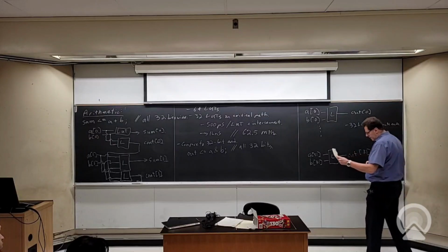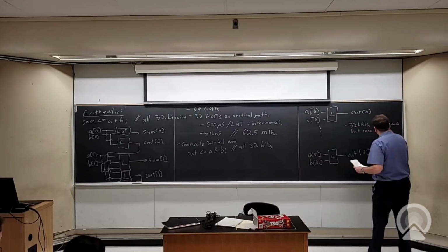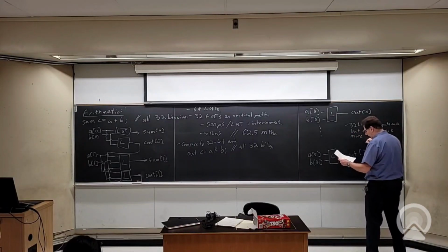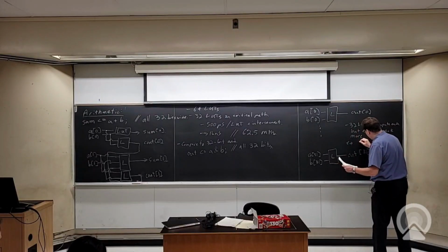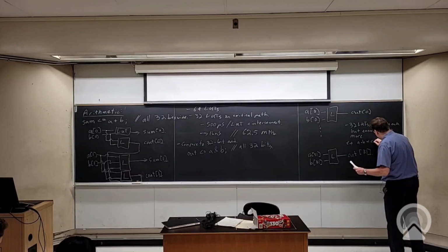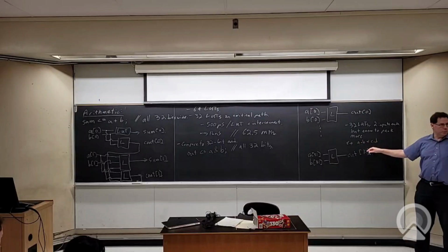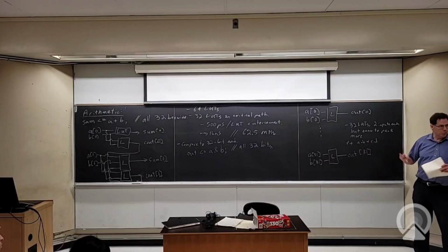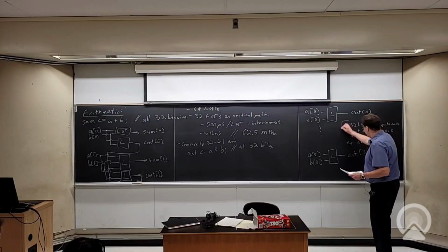Okay, so basically, but easy to pack more. You know, so for example, if this was in something like A and B or C and D, now I can pack all this stuff together in one LUT. It'll use all 4 inputs. So I could do all this instead of the A and B, and it won't cost me any more stuff. And there's a pretty reasonable chance I'll find something like that. Okay, so that's our area.